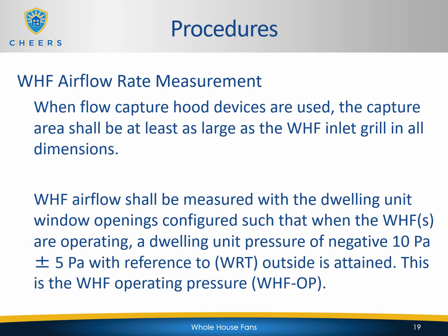So as we mentioned, when a flow capture hood device is used, the capture area shall be at least as large as the whole house fan inlet grill in all dimensions. So it's going to be either equal to or larger than. It cannot be smaller.